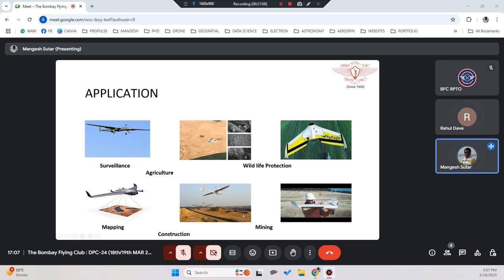In that scenario, where the area is bigger, the small rotorcraft drone will not be able to capture, because it has very little height, and it is not able to capture more area within that time frame. See how many flights you would require if you want to cover, let's say, a thousand acres of land. That will not be done by a rotorcraft, so it has limitations.